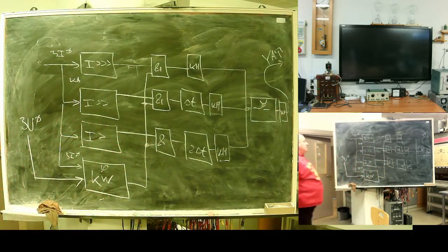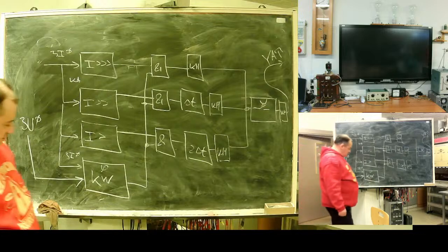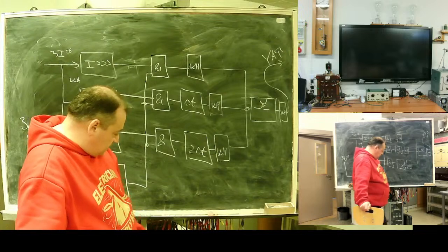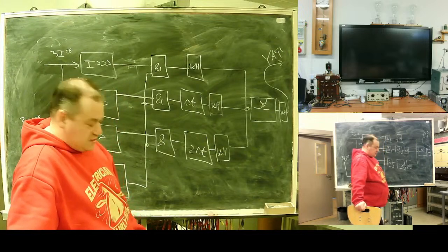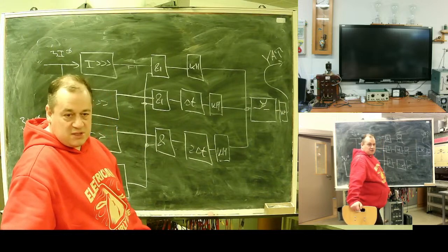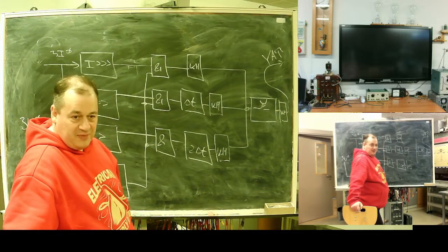Here is block schematic of earth fault protection. Set of current relays, one angle relay and function, and set of time delays. Here stands last operated electromechanical earth fault protection in Latvia. This one was the last commissioned one.